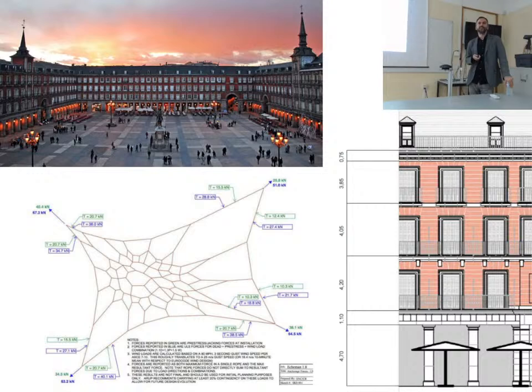They told us the buildings are protected. It was not possible to connect to the buildings, so we had to provide an auxiliary temporary structure to be able to place the piece of art in position. Below the plaza we have a parking garage, so this is a concrete slab. We don't have soil below, so we have the challenge of big horizontal forces because it's a membrane.